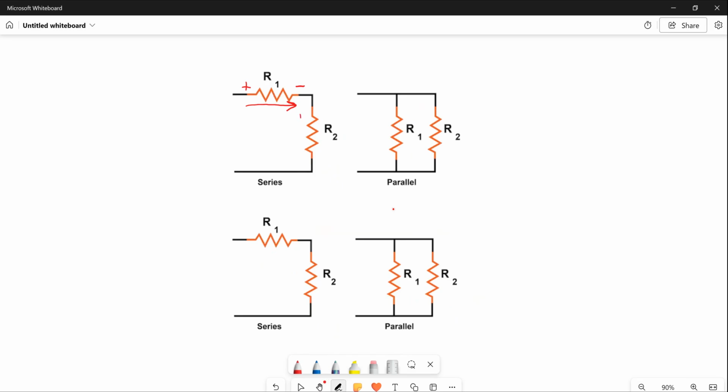Obviously, the current in a series circuit is going to continue, and the passive sign convention will show a positive at the top of R2 and a negative sign at the bottom. Current always enters the positive terminal of a passive element and it leaves on the negative terminal. That's because the passive elements have to exhibit voltage drops. There has to be a drop in voltage conventionally.